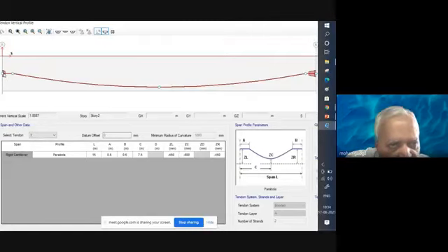At the left support and at the right support, I have considered the cable to be positioned at the center because I have a total depth of 900 millimeter. Out of that, I am considering from top a distance of 450 at the left support and 450 at the right support. So I need to consider this distance 450, this distance 450. In between, I have taken a parabola. You can see this curve as parabola.